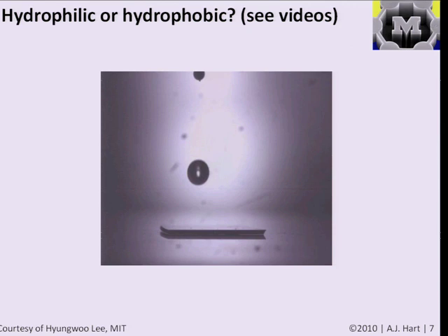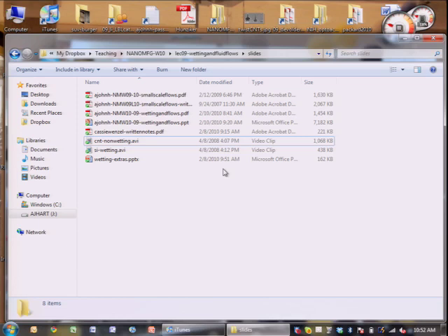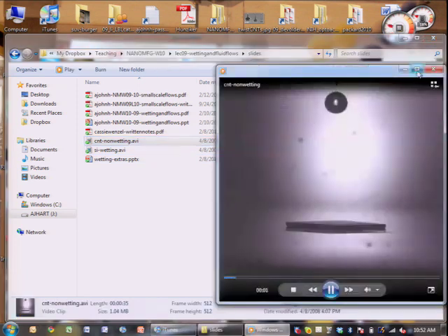So I just wanted to show you a couple of videos. When people study interfaces between solids and liquids, you want to measure the contact angle, and you sometimes use what's called a contact angle goniometer that has your surface, a good light source and a good camera and lets you get a picture of the situation. Let's look at a video that compares the behavior of a non-wetting surface to a wetting surface. This is taken with a high-speed camera and slowed down.